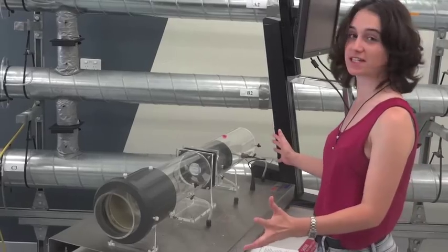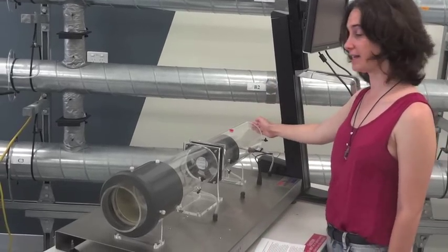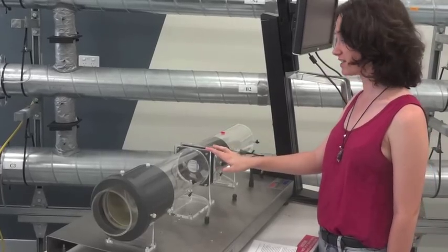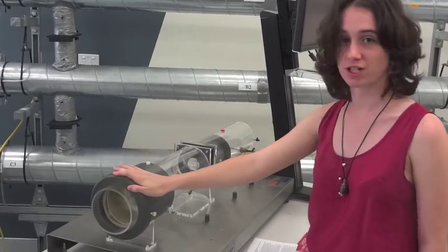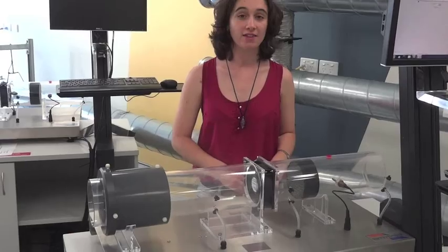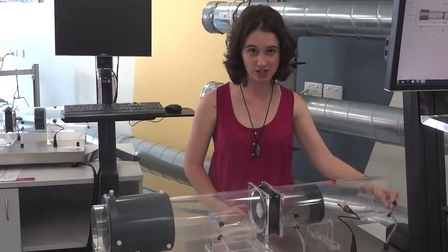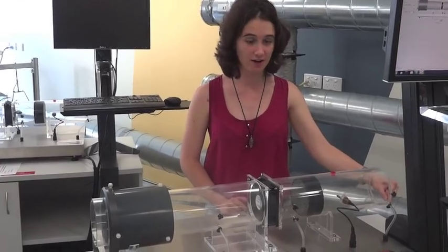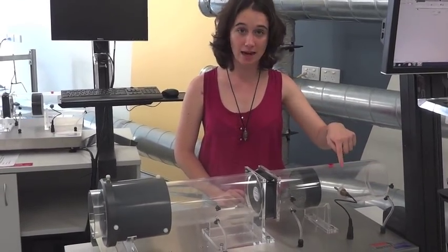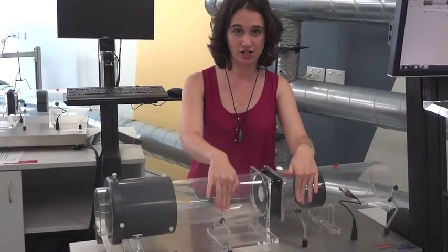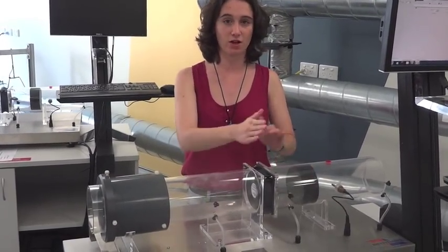The components of the duct are this orifice plate, a straightener for the air, a fan, an axial fan, and an aperture device at the outlet. There are 4 sensors that are used in this duct. The first is a pressure sensor right at the start of the duct. The next is a temperature sensor for the density. These next two are also pressure sensors that measure the difference over the fan.